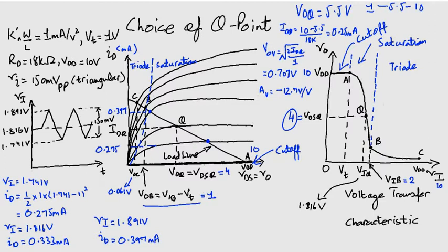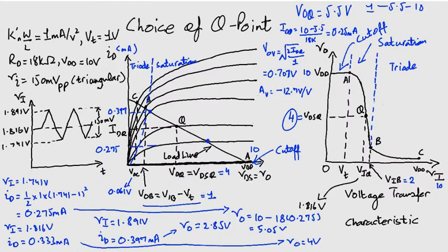Using these, we now calculate the voltage values. These are the output values at the bottom of your screen. Let me write them on the graph. There you go. Take a look at the two values that are just included in the middle graph. These 2 points are also shown on the graph to your right, that is the voltage transfer characteristic, and I have shown the output swing by coloring the segment blue. And you can see that the extremities of the region lie inside the almost linear segment.